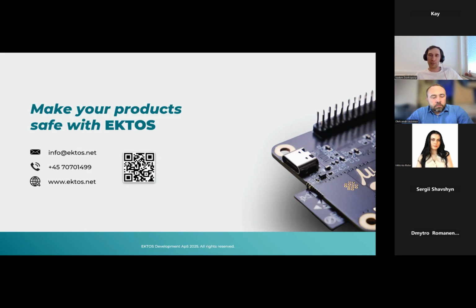So you have to produce a lot of units. You have to have an established procedure for getting faults, analyzing them, and calculating the fraction of dangerous undetected faults in your product, and the frequency of occurrence of these faults. And afterwards, you can say, okay, this is proven in use.